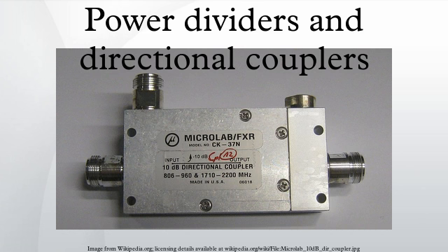The coupling is given by the formula, where N is the secondary to primary turns ratio. For a 3 dB coupling, that is equal splitting of the signal between the transmitted port and the coupled port, the isolated port is terminated in twice the characteristic impedance, a 100 Ω load for a 50 Ω system. A 3 dB power divider based on this circuit has the two outputs in 180° phase to each other, compared to λ/4 coupled lines which have a 90° phase relationship.